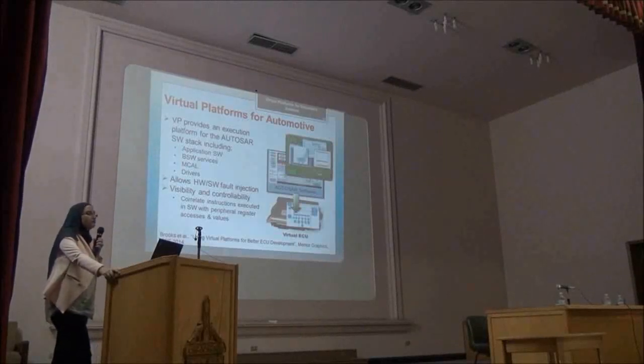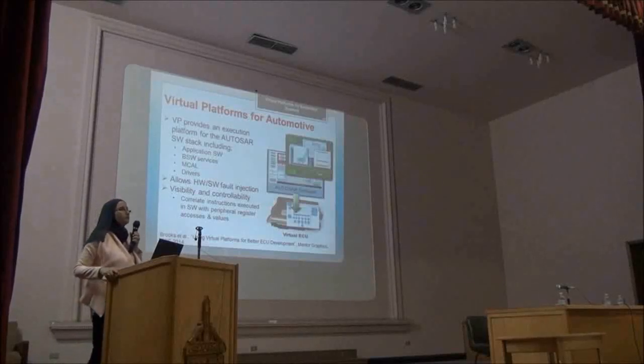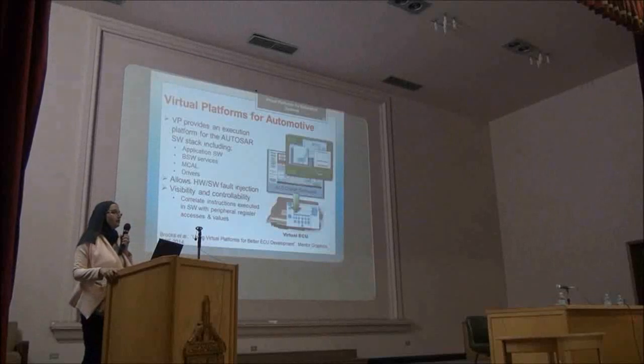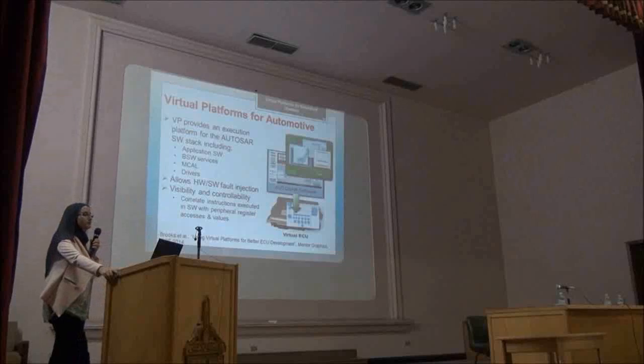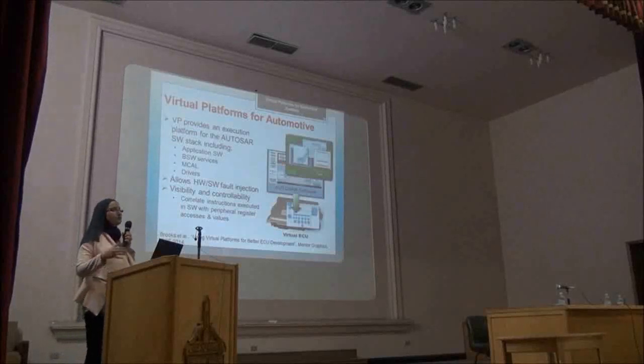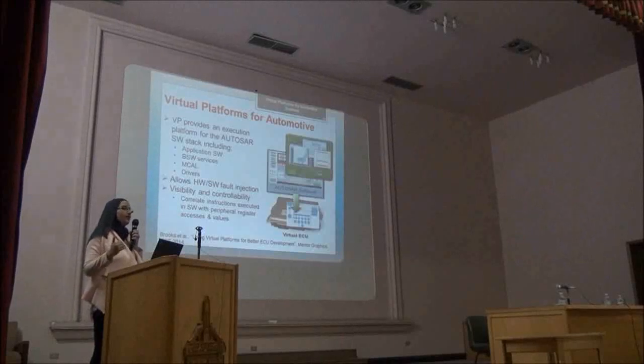It enables you to inject hardware and software faults in order to test both the ECU at the hardware level and the software targeting the ECU. It gives you visibility and controllability. You can execute instructions in software and see the values of registers and how hardware models behave for this software.